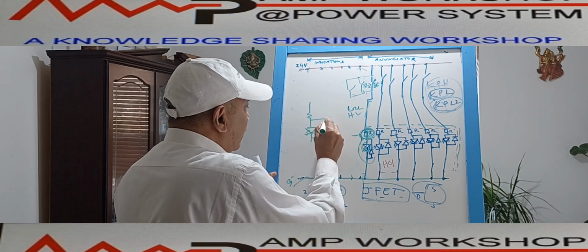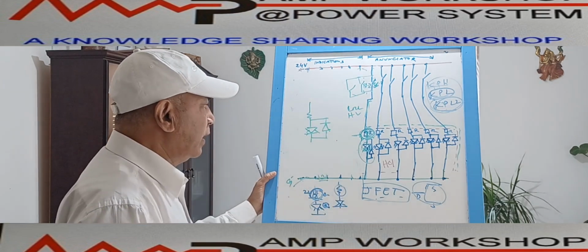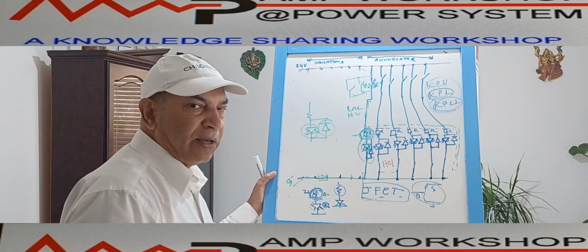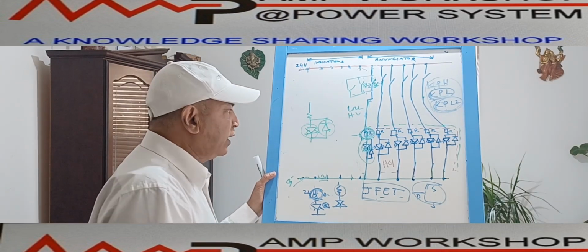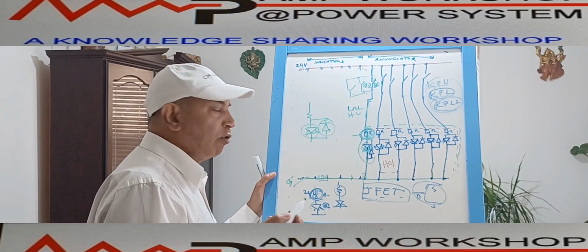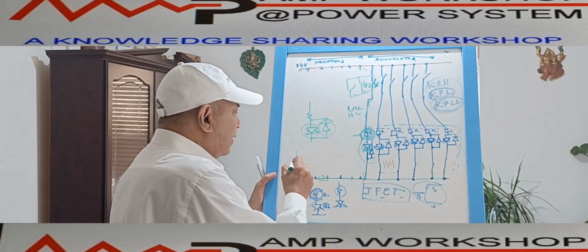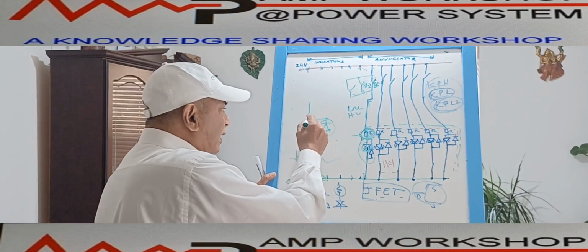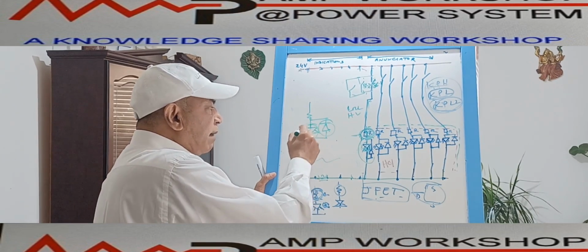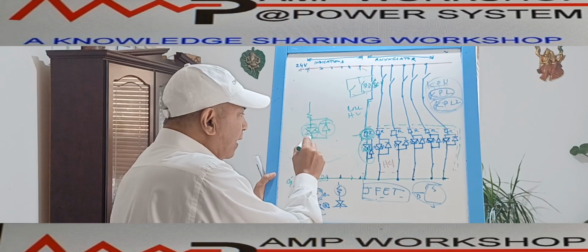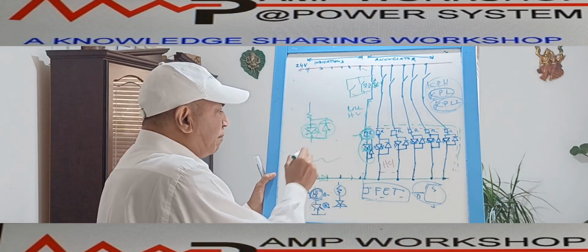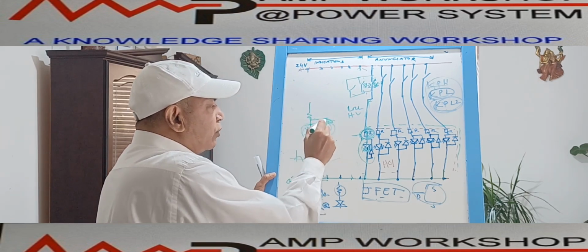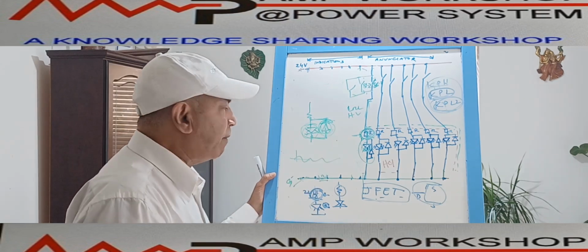A reverse bias diode is connected in parallel to this. The reverse bias diode actually protects these LEDs. If there is a voltage change or a ripple, or any other current flowing, ripple means it is an AC with multiple different frequencies that can pass current. If that current passes through this, it will cause damage to the LEDs. So we give a reverse path to pass the negative part of that current flowing through the LEDs, to get a drain. Okay, so this is one function.